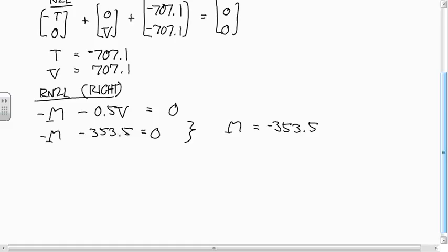So this is the idea of internal loads. The only thing that we have to add to it now is we have to be able to calculate the internal loads for every value of X along the length of the beam. All of these problems I just did for a single value of X. I just did it halfway through the beam. That's not enough. So we're going to have to come up with functions of X to tell us what these internal load values are as you go from one end of the beam to the other one. So that's what we'll do next time. Okay, that's it.